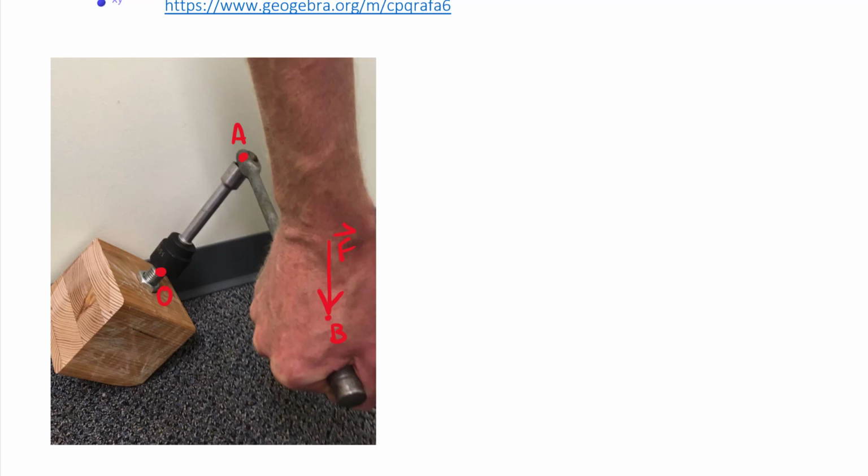You could think that we're trying to loosen that bolt, and it lies upon a line that is 30 degrees from horizontal. From here up to here is 30 degrees. Hopefully that gives you some physical context. Of course, the moment that we want to remove that bolt is along line OA. Any other moment that exists from us pushing down at point B is not the moment we're looking for. It will still exist, but we want to know how much moment we're getting along line OA, so we'll compute that.